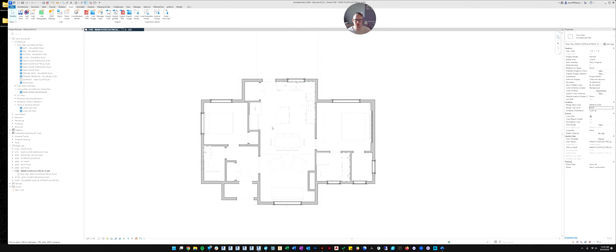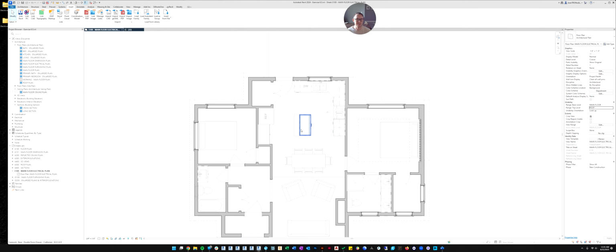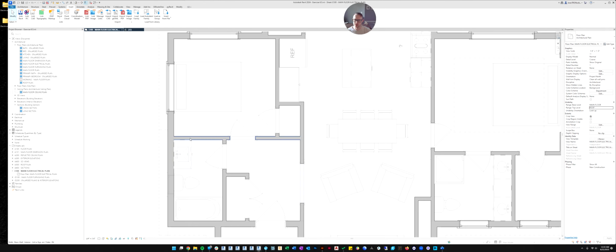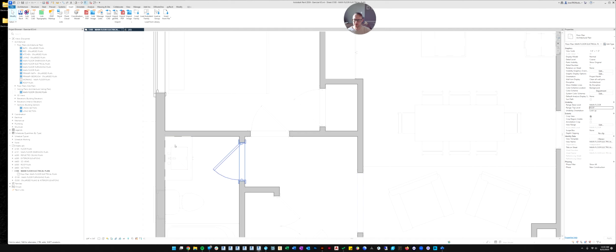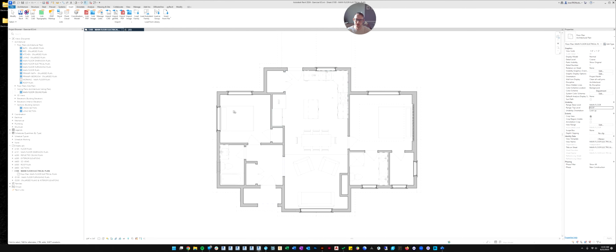It's just that you'll have more settings and opportunities to make changes. The lights look just a little bit better and they'll function better. So if you remember, one of the things we struggled with before was if we made a light switch or an outlet too high on the wall, it disappeared. These families won't do that. It doesn't matter what your view range is. It should show the light switches and the outlets. So that's one less thing you have to worry about.